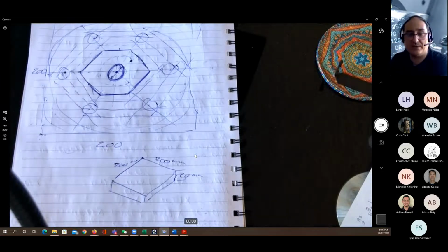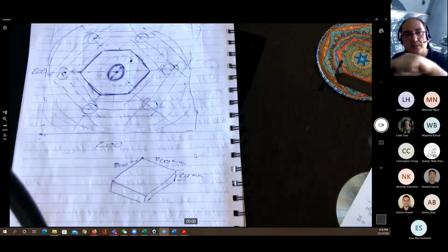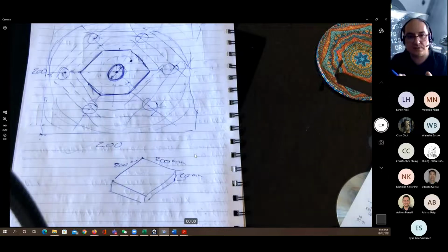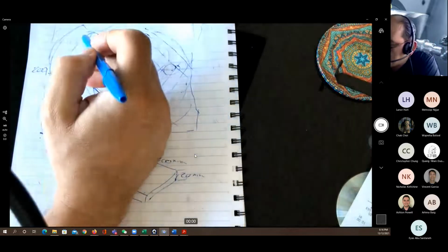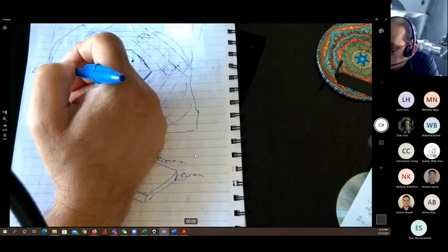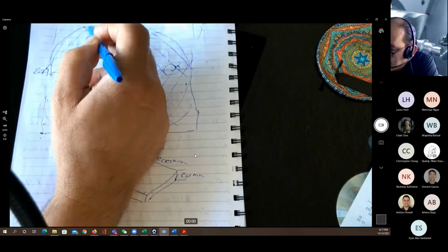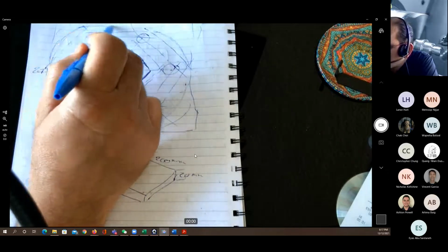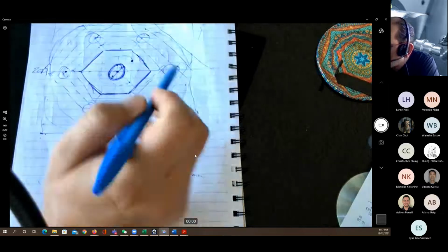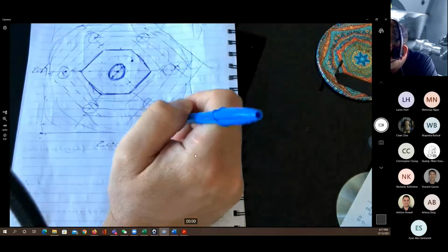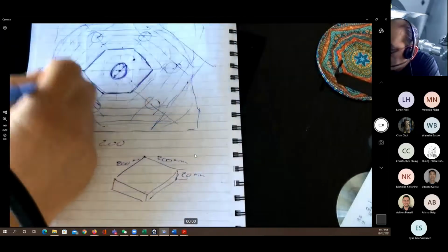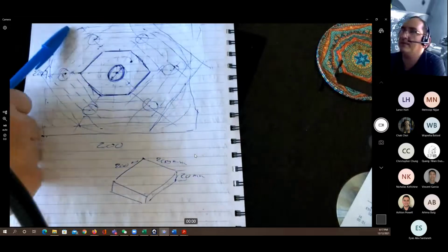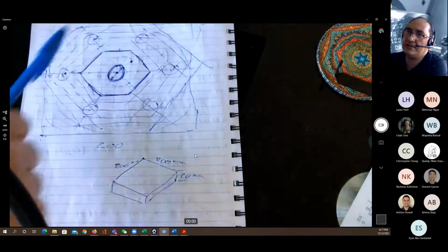So basically what we are going to have here is not only face milling, but it's going to be profile cuts continuously. Every time we're going to get closer, closer, closer, until we have a hexagonal shape left in the middle. Now, I'm not going to stop until these lines are moving outside the work part. So you can see that I did that, and obviously I'm going to need another cut at the outside to remove this part till here. Okay, so I just keep doing that.